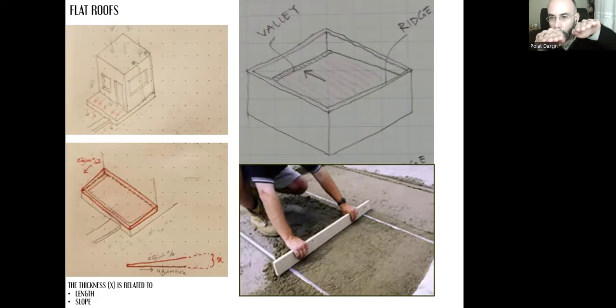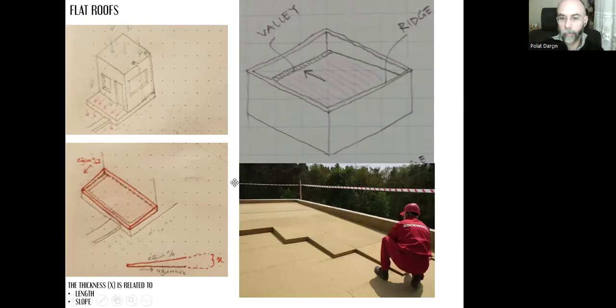Now I'm creating a slightly sloping surface, and I don't want my leveling concrete to get very thick like that, because all this leveling concrete, the sloping surface, will be resting over the floor slab. And I don't want a very thick layer of sloping surface because as it gets thicker, it will become heavier. I don't want a heavy layer over my floor slab. For that, to decrease the weight of this layer, I need a thinner slab. I don't want a very thick